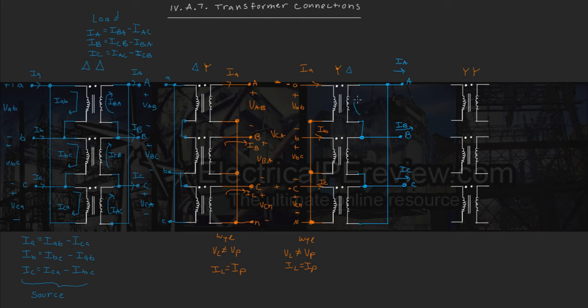We're going to draw our phase currents. We're leaving the dot since this is our node polarity for our load. Up top here, because we're going from B to A, is phase current BA. Again, capital because it's a load. Our second phase, we're going from line C to B. So this phase current is ICB.